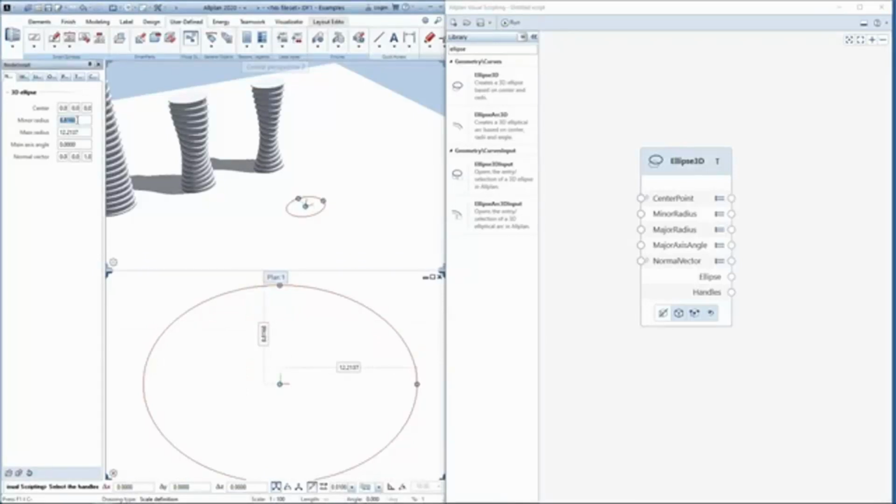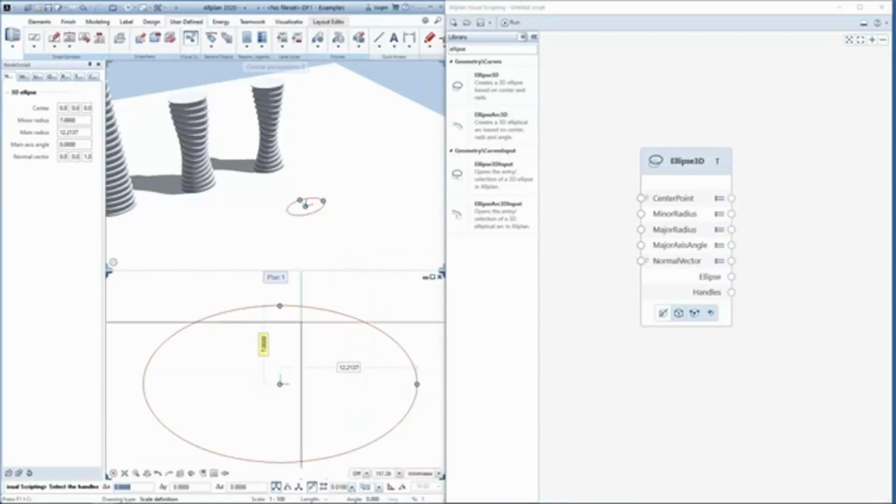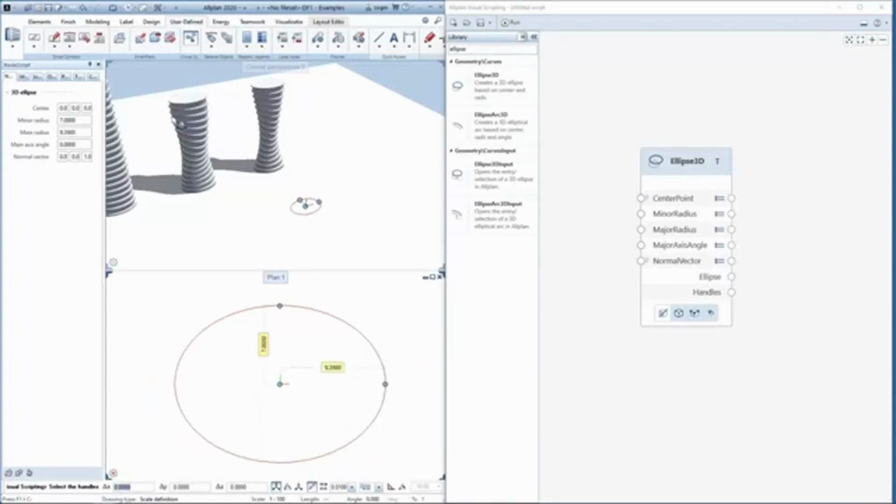And you can even type a unit in this area, like let's say 700 centimeter, and it will automatically convert to the local unit which you have set here. For example, we have meters here. And for the customer from US, we also adopt a US customary unit. Let's say if you want this to be 30 feet and 10 inch, you can just type it like that and it will be automatically converted.